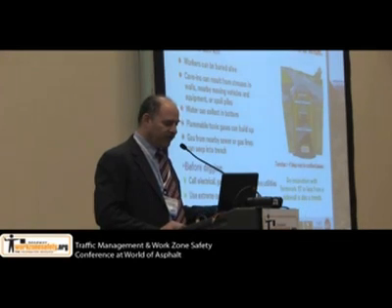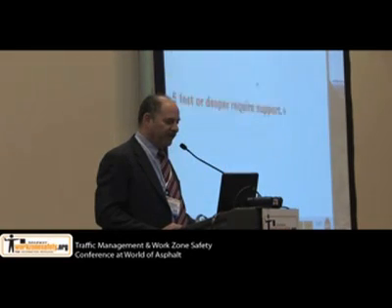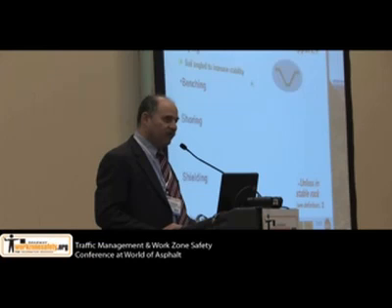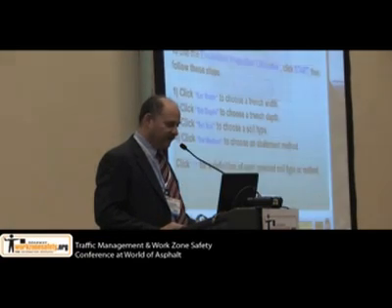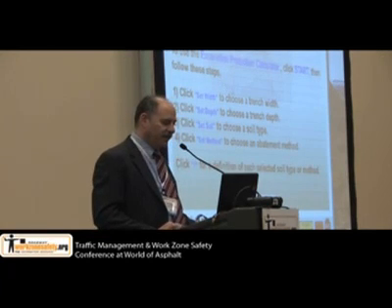So first we define what the hazard is, and then we have 2 slides talking about how you prevent cave-ins, because most of the trench fatalities come from cave-ins. You can slope the soil, and we have a demo here. This is an excavation calculator to show people the difficulties or what it takes to slope appropriately.